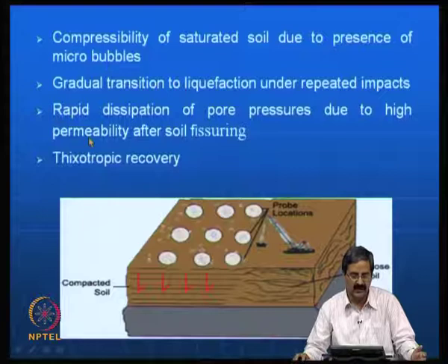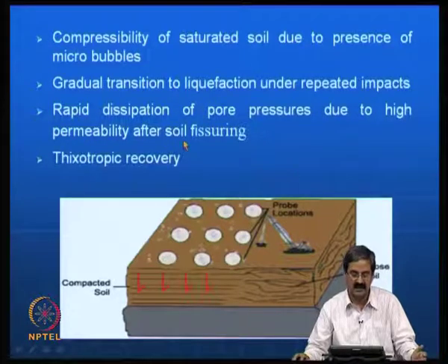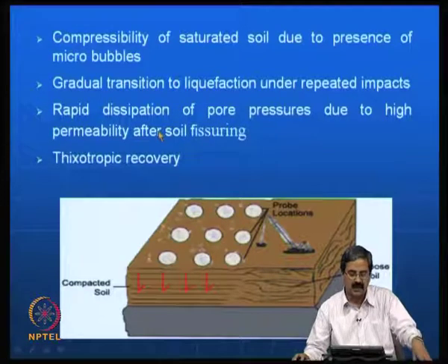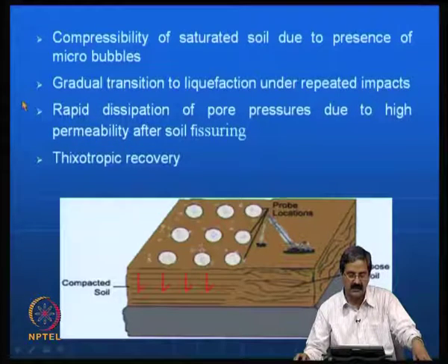So, what we do here is that you can see the rapid dissipation of pore pressures due to high permeability after soil fissuring. This is another mechanism that is always present, that there could be some small fissures in soils that lead to higher permeability, and that higher permeability leads to rapid dissipation of pore pressures.